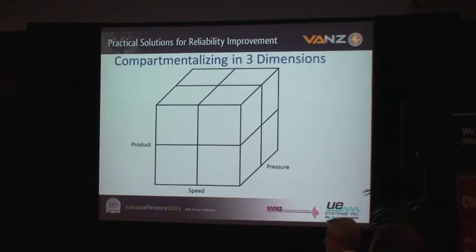And when you go out with your vibration data collector, because you've got different nip pressures, there are just so many different parameters that affect how that machine sounds and how it vibrates, that there is no possible way to do any meaningful condition monitoring and evaluation without knowing the nip pressure, the speed, the temperature of the feedstock, the viscosity of the feedstock. It's just amazing. They tell me it's like night and day in the sound when you walk in the building. Oh, we're making bathroom tissue today, or kitchen paper towels.